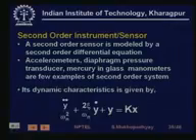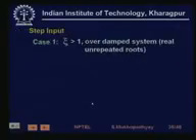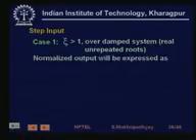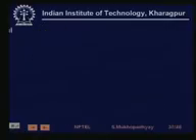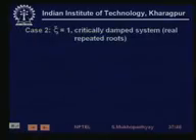So its input output dynamics is given by a second order differential equation as shown, in which there are two parameters. One is called the natural frequency, another is called the damping factor. Again, its response to the step input. In this case, we have three kinds of cases depending on the damping factor. One case is when the damping factor zeta is greater than 1, in which case we call it an overdamped system, and this is the expression for the output time function. We will just see the case and then we will see the plots.